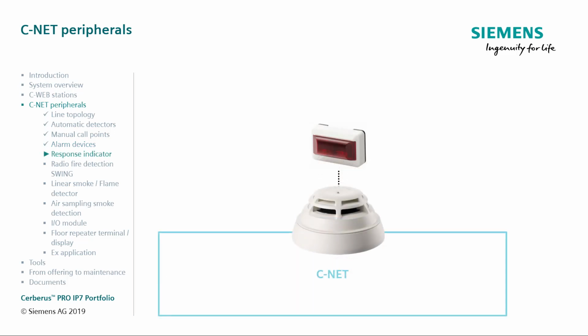The external alarm indicators are connected to fire detectors so that they can quickly indicate the source of an alarm signal from detectors which are not easily accessible or visible. You can configure when the external alarm indicator is activated. It is possible to activate the external alarm indicator in parallel to the detector's internal alarm indicator, or by using a zone alarm, or with an independent control.